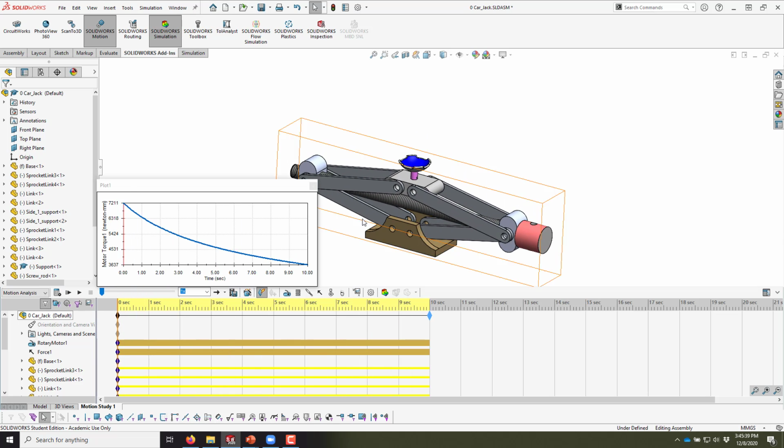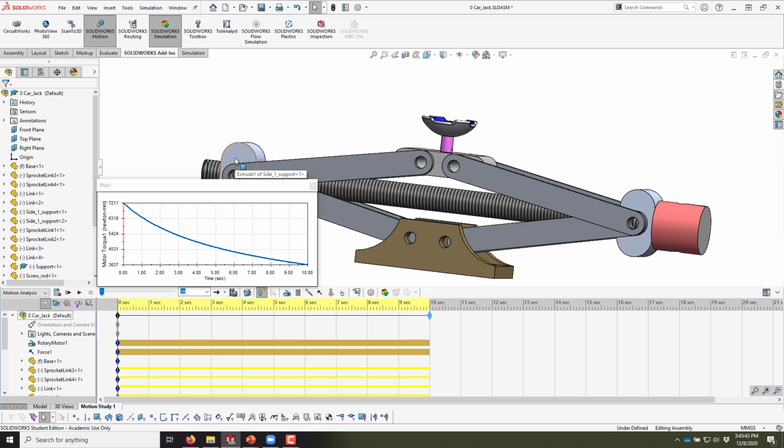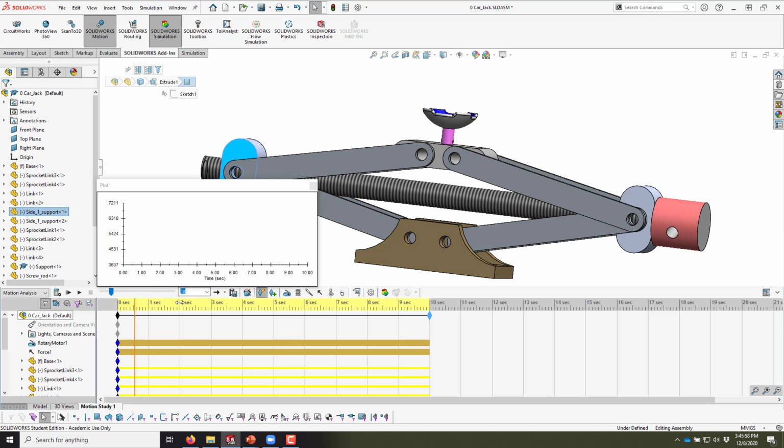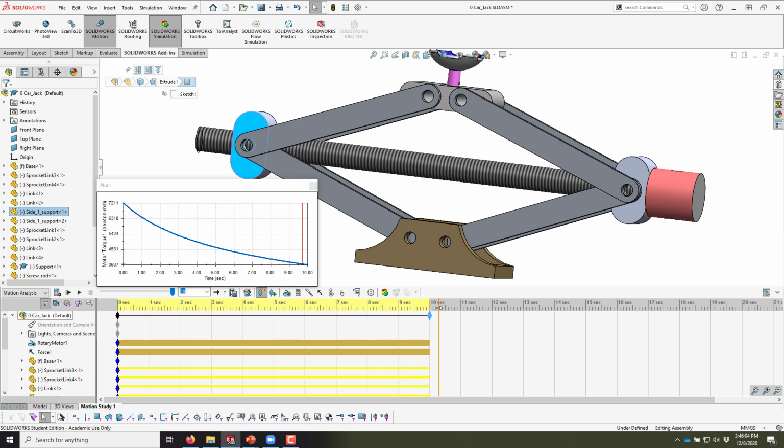I think that makes sense because, when you look at it, think of it as like we're pulling on this. When we're rotating this, we're pulling on it in this direction. And you can see the distance between this axis and this guy is pretty small. It's like we don't have much leverage. And then as we move along, we get more and more leverage. Picture now we're pulling on that, but now we have a bigger lever arm. Okay, so that's the kind of behavior we're getting.